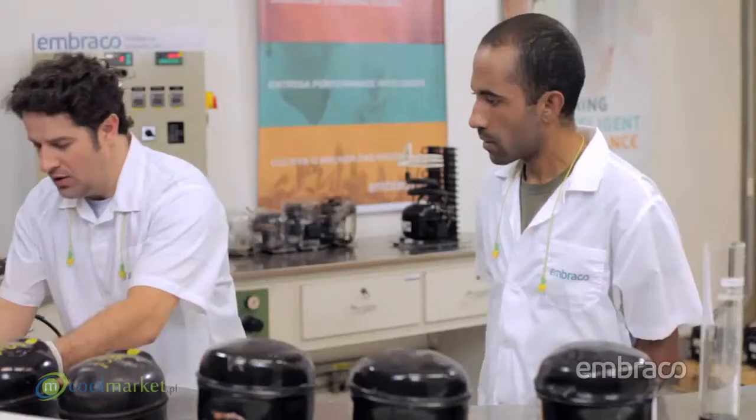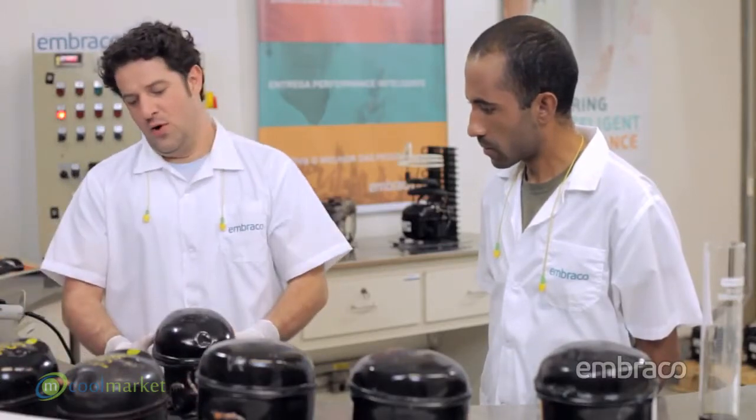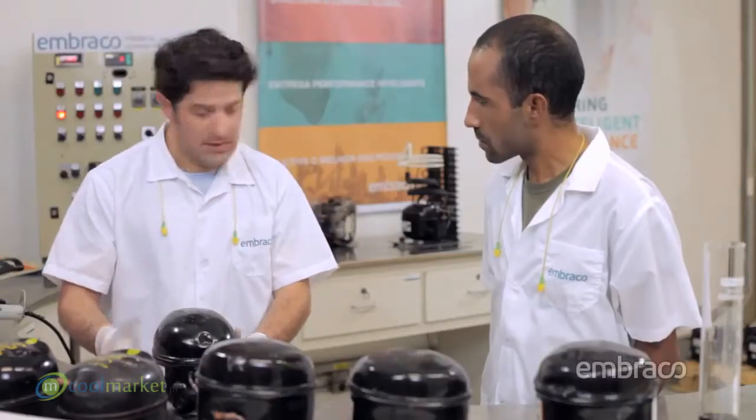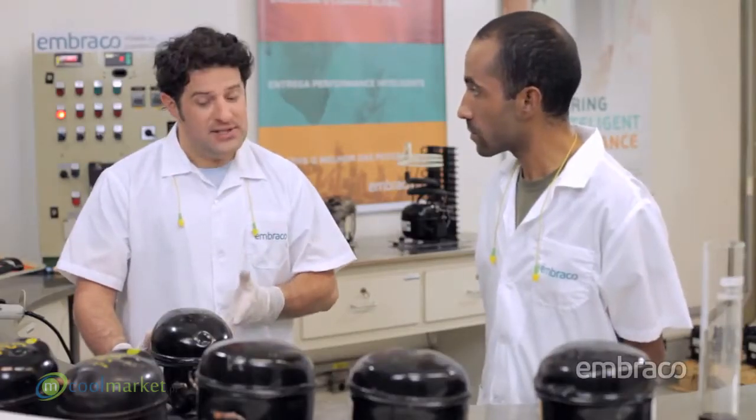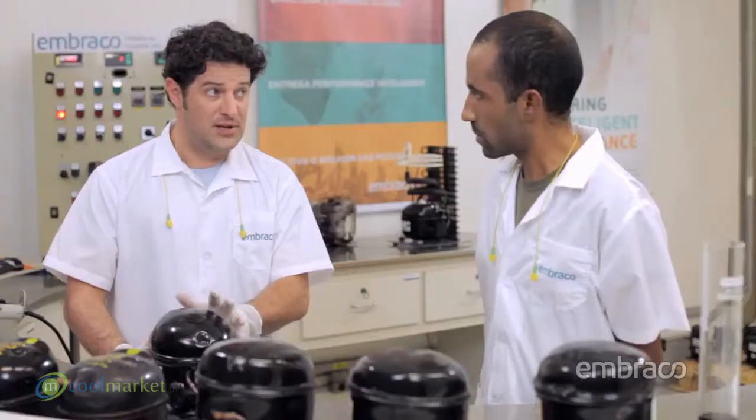Oh, and the second one here? One of the common problems is related to the presence of moisture in the system, which can occur in various ways. One of them is through a poorly done vacuum process. This process is extremely important and must be taken seriously. A vacuum pump suitable for this purpose must be used, with capacity greater than or equal to 5 CFM.